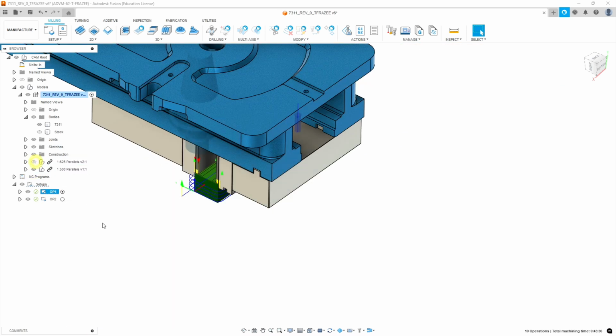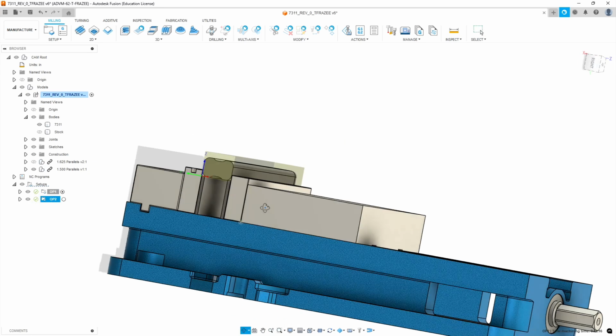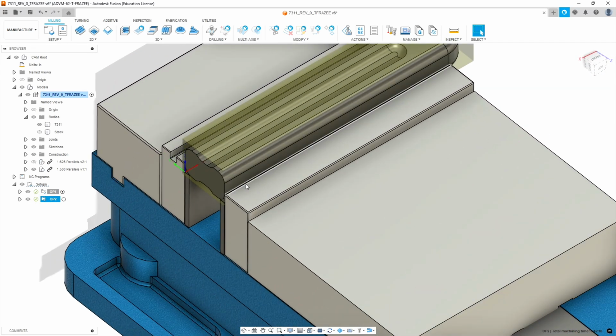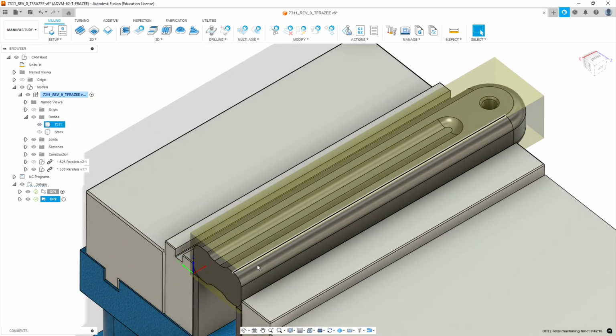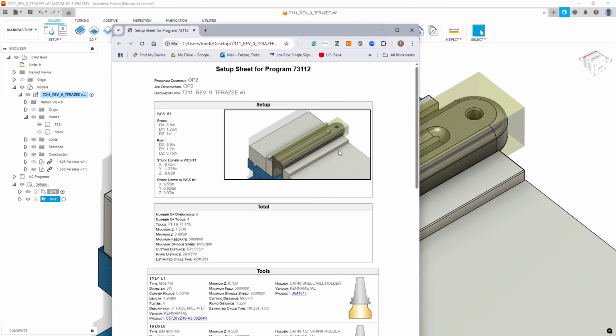We're going to make the second side vise visible. Flip around. Highlight the second operation. Position the model and the vise in a way that you can see the origin, your work coordinate system, and see the blank in there. So now we're going to do a setup sheet. It should look something like this. You're double checking all your numbers. This one's 8,000 RPM too. Our minimum Z shouldn't be any less than 0.495. If it's lower than that, we've got a problem. Here are the tools that you need to put on your traveler sheet. Work coordinate system 1 on a Haas is G54.